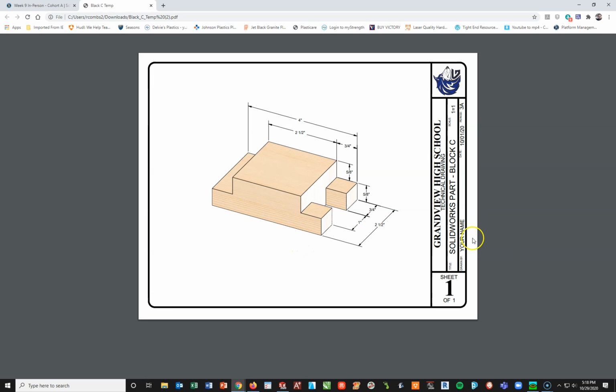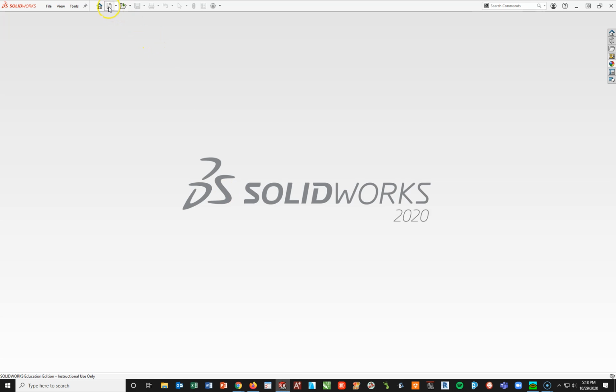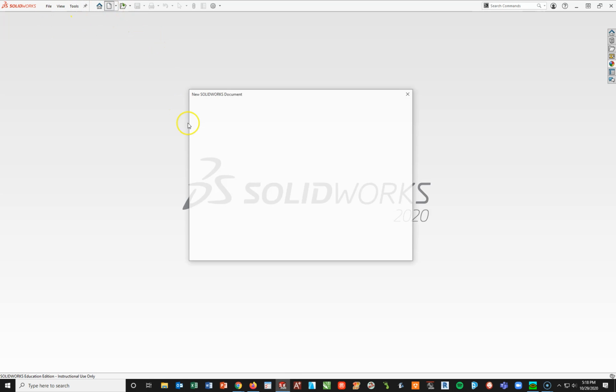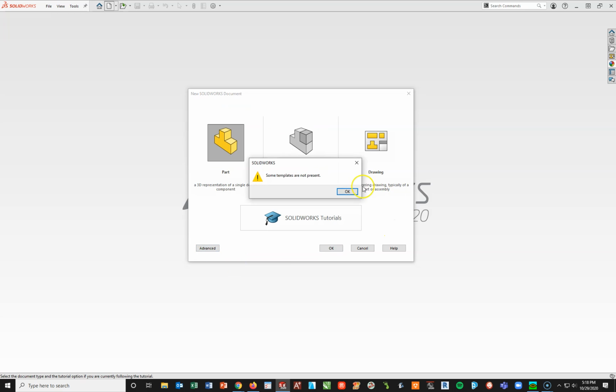Okay, what we're going to do in this case is start simply with drawing a front view. So we're going to go on the front, and we're going to create this outside shape and extrude it back into the third dimension. So instead of drawing on paper now, we're actually going to go into our SolidWorks and draw this. I'm actually going to go File, New on this one, and yours opens this way. What we'll end up doing is double clicking the word Part.